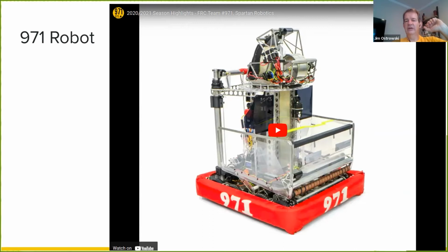And then we added 1 camera in each orthogonal direction: forward, back, left, and right. There's an additional camera, a little bit hard to see, but you can see this one here, which is slightly elevated, tilted up, but looking forward. And then there's one on the left, one on the back, and the right. So it gives us coverage. No matter which way the robot is facing, ideally there's some camera that's seeing the target, as well as the turret camera. So that's how we set the system up.